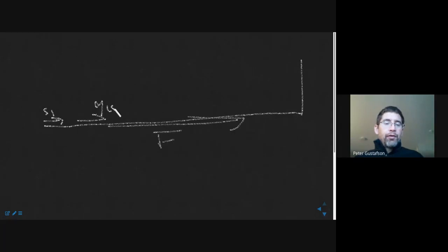So this is Q of S and F1. Note, I drew them all at exactly the same time so that I never had any confusion about which direction they were, because we don't want sign ambiguity. The forces are always defined with respect to the relative coordinate system with the equation we're doing, and then we let the force balance keep track of the sign for us.